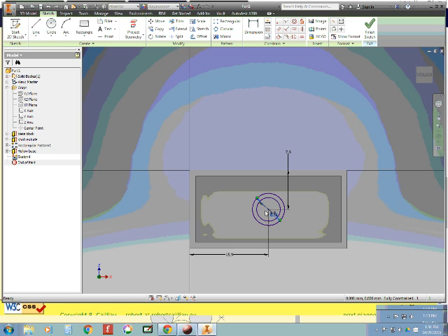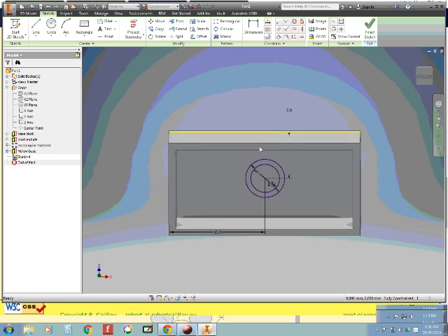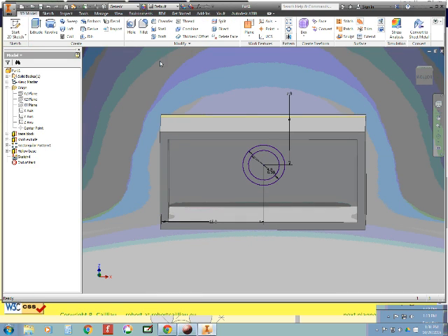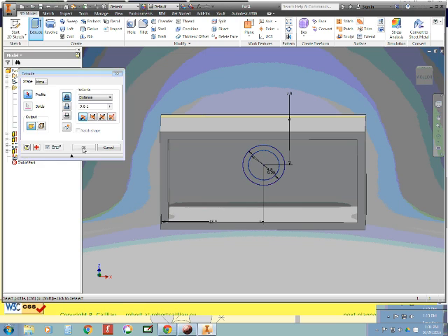Okay, so I'm going to go ahead and extrude, so I want to right click and choose Finish 2D Sketch. And there's my extrude tool, but once again I like using the right click option and choose Extrude. And I've got to select what I want. It doesn't know exactly what I want to extrude. I want to extrude the space between these two circles. And look at that. It remembered that distance that I extruded here, the 9.6 minus 1.